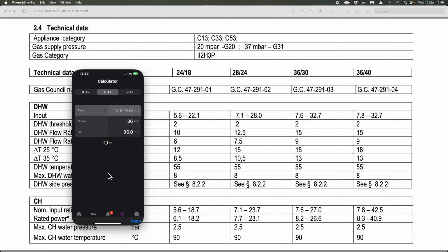Setting it up like this, you guarantee that you're getting maximum efficiency out of your hot water side, and you'll get your boiler in condensing mode because you're keeping it under that 54 degree dew point, and you're not ever going to get any complaints of difference in flow rates or anything along those lines at all. So it's a good way of setting up, and what do we say? Be a pro if you can.